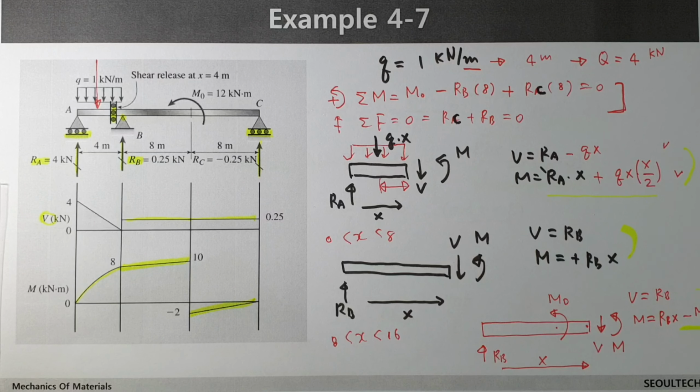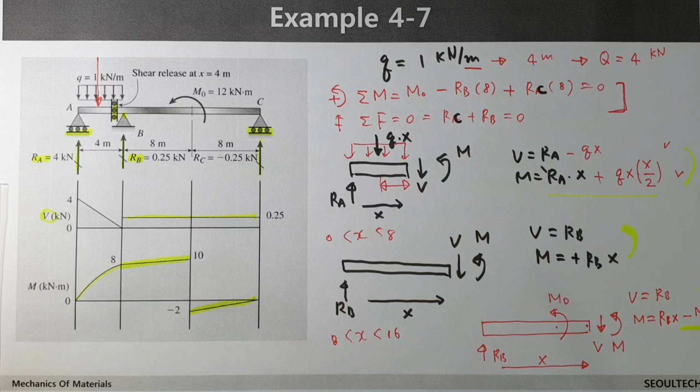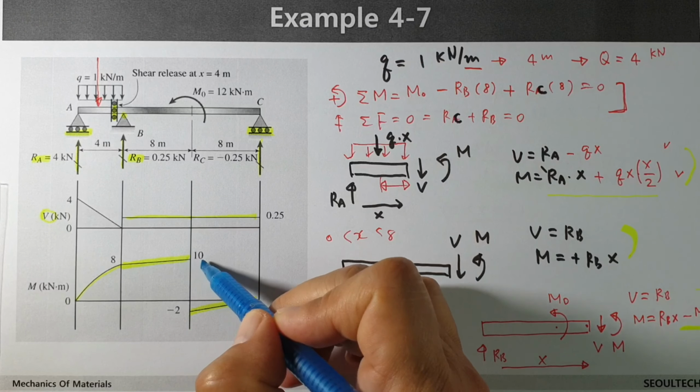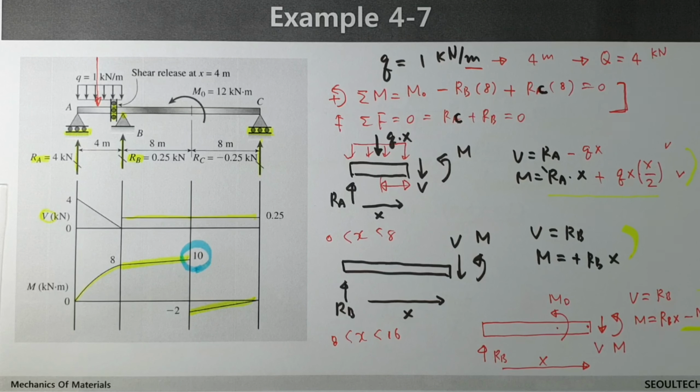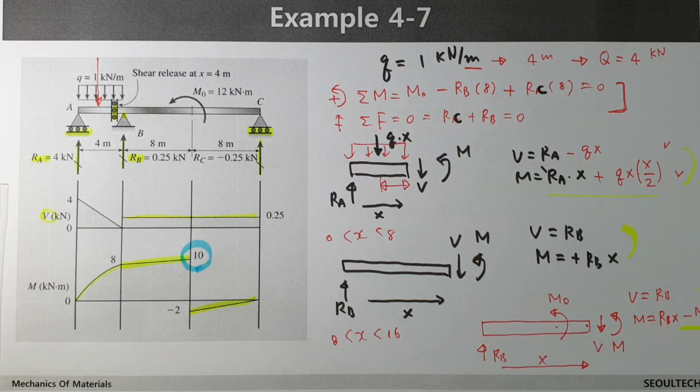Anyway, when you consider every case, then we can calculate shear force and bending moment. And finally, when you plot, then this kind of shear force and bending moment diagram. And when you consider bending moment diagram, this point is the maximum bending moment we can have. Okay. This kind of maximum bending moment is considered later on to calculate stresses and displacement inside the beam.